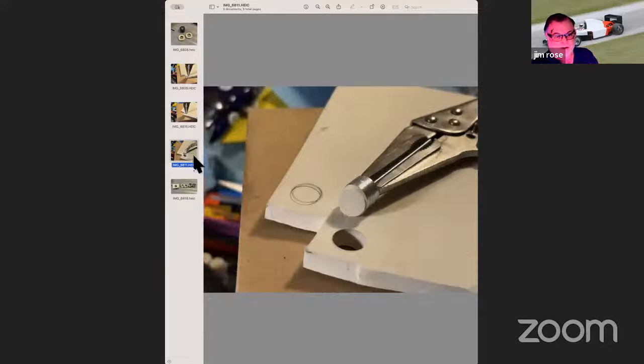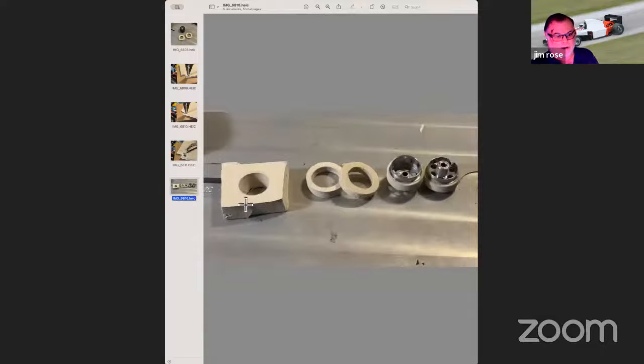So then I take that sheet of rubber and cut it in a square like that, and then mount that on that same wheel without the ribs on it, and turn it down to a much smaller size, split it in half, mount it on the tire and then on the wheel, and then cut it down to the actual size that I want the inserts.